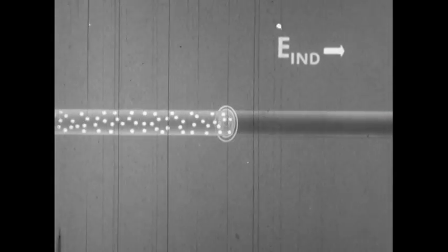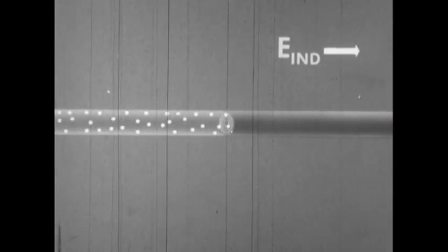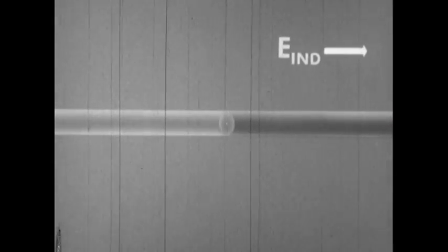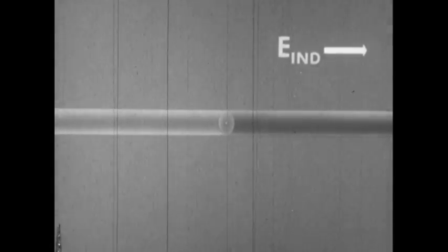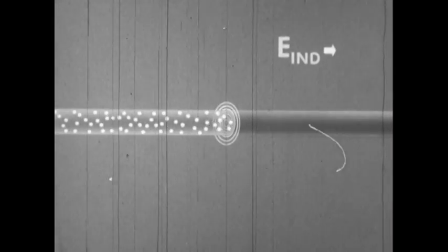When current and field pass through zero and change direction, the field is cutting the wire at maximum speed, and the induced voltage is maximum. This induced voltage that continually opposes any change in current is called the EMF of self-induction.